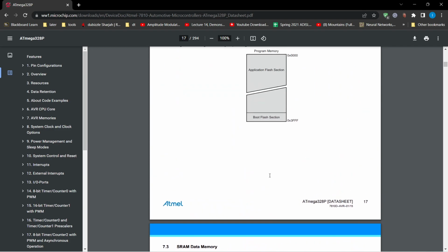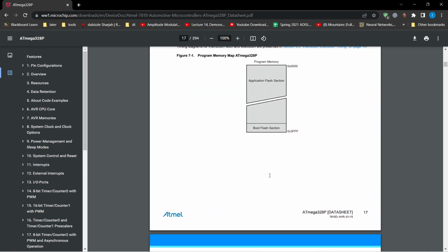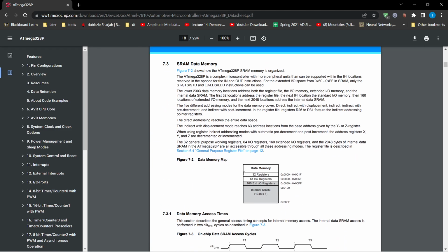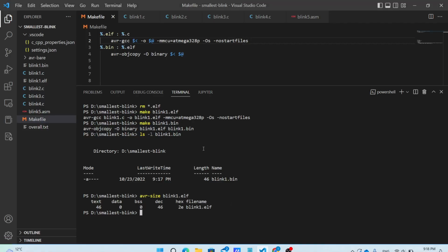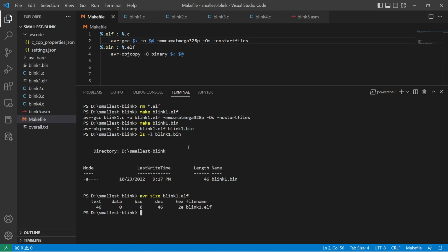So normally it is the startup code that takes care of relocating the global variables into the RAM. But in this case, we don't have any global variable. That's why we did not see the code that relocates it. Also, the startup code is responsible for clearing the BSS section. Maybe one day we will see that.